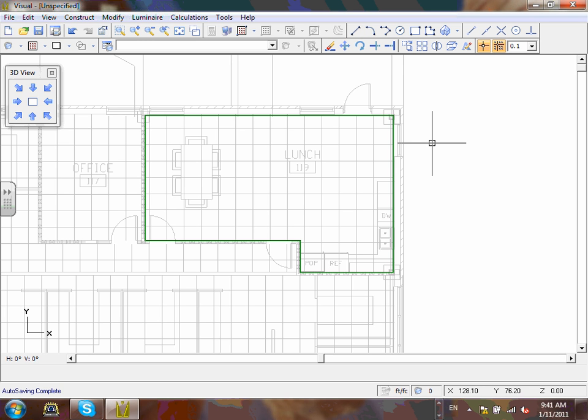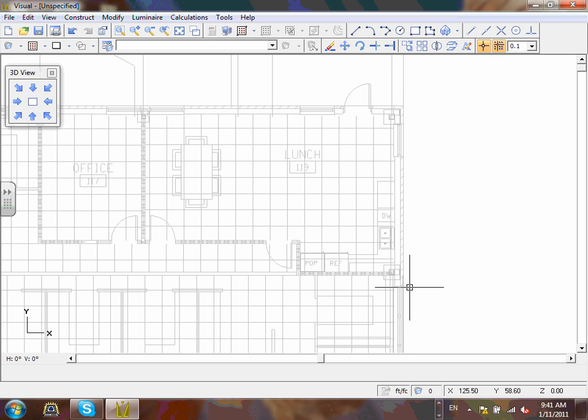Okay, so this room, let me delete this one more time. Hit enter or right click. Okay, let's start one more time, guys. If you can't see what you did, please look over here. This is all your solid right here. Make sure your solid are set at editable. You might have accidentally set your solid at uneditable, so whatever you draw, you're not going to see it. So make sure that it's editable.